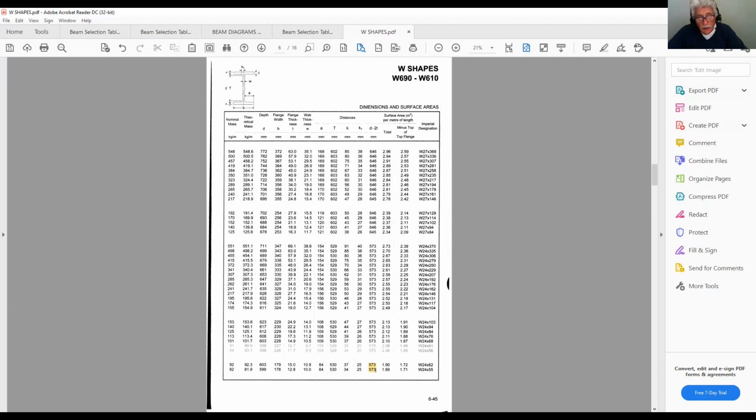Then we can go back to here and put a knee brace, 1, 2, 3. So at 4 meters, we can laterally support the bottom one, 1, 2, 3. Here we have to do it on both sides, once there and once there. Therefore we can bring down our LU to 4,000 if we want to put that in.